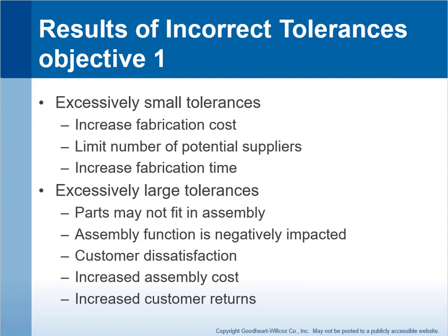On the other hand, if your part tolerances are too large, your parts may not fit when you go to put them together. Assembly function would be negatively impacted, and that would lead to customer dissatisfaction, increased assembly costs, increased customer returns, and all in all, bad for business.